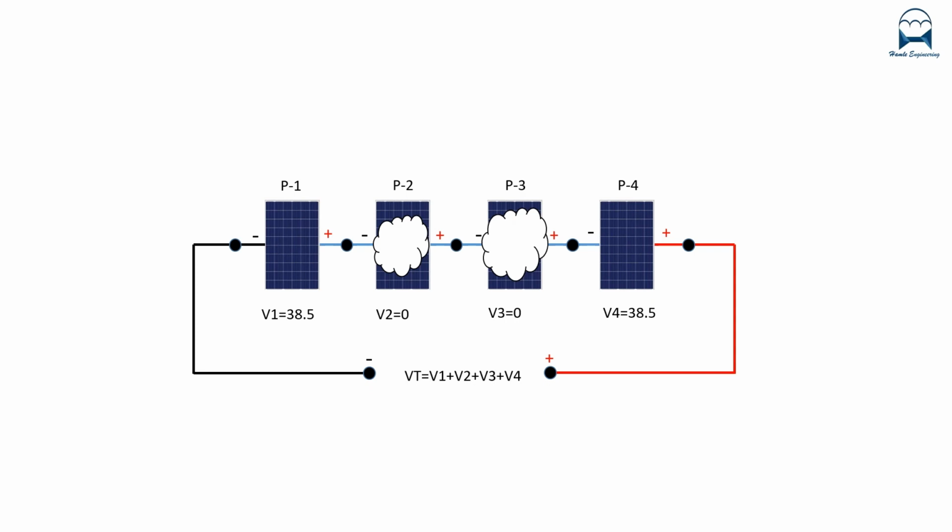Traditionally, solar panels are connected in a series of parallel strings. This means if one panel is covered by shade from a cloud or tree, then all the connected panels within the string will also lose power. This is because the panels are wired together in such a way that the output is reduced to that of the weakest panel within the system. Shading just one cell in a module by half causes the output power of the whole module to fall to half. No matter how many cells there are in the string, completely shading one cell will cause the output power of the module to fall to zero.